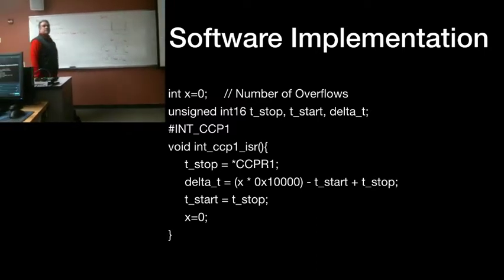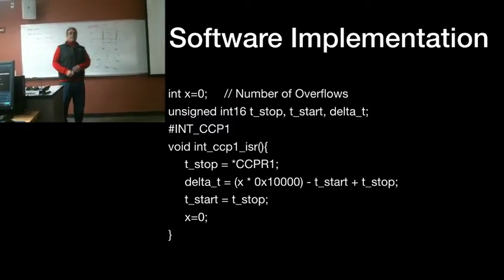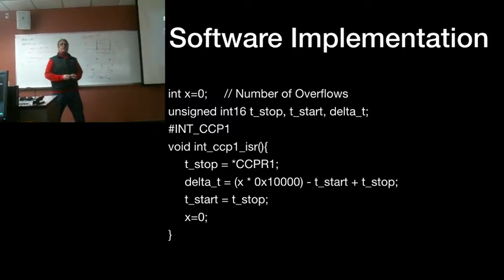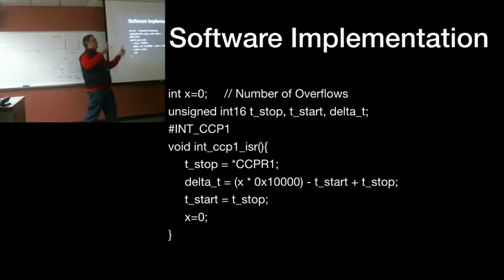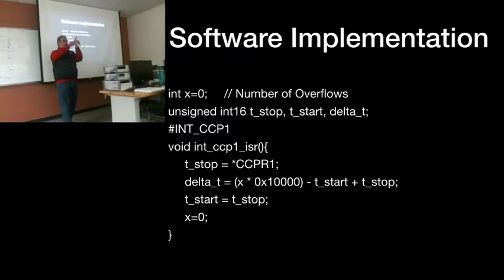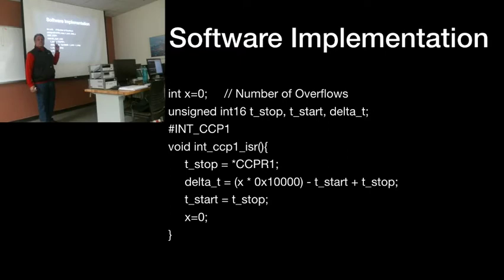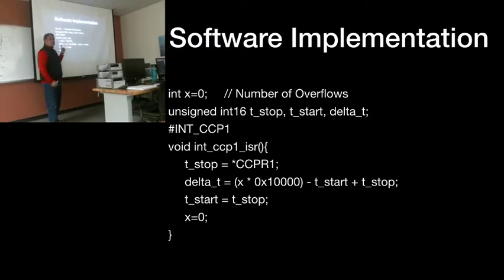That's it, just 4 lines of code. This is taking care of those cycles that are showing up. So something comes up, I grab the time that it happened, I compare it to the past, and I cyclically do this over and over and over again. So that means that delta t, now listen to what I'm gonna say, because this is gonna come back to haunt you. Delta t contains the number of time counts between 2 events at C2.